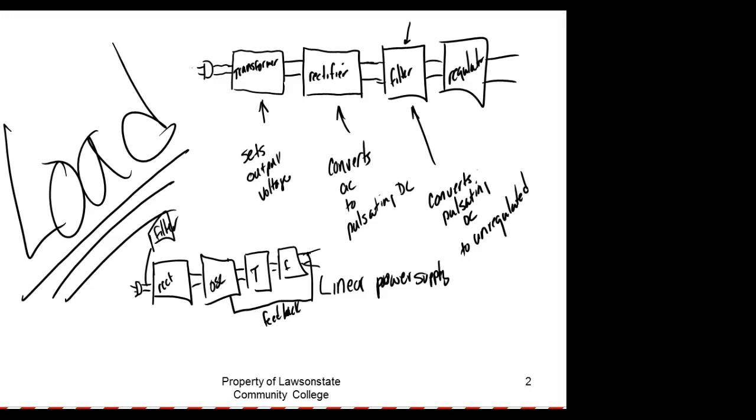Switching power supplies are harder to design, and they're hard to fix because they depend on feedback. If it doesn't have feedback, it's supposed to start oscillating. It's supposed to have what they call a startup circuit, because you don't have any feedback to start up. So if it doesn't start, you don't get feedback. You don't get feedback, you don't get regulation. But you don't get feedback, you don't get startup, right? So you get in what we call a troubleshooting loop, where everything measures right for it to start, but it just doesn't start.